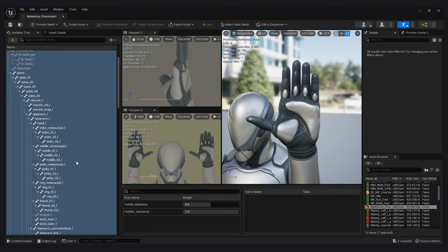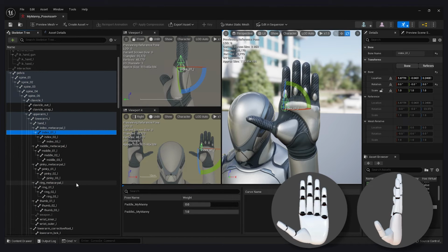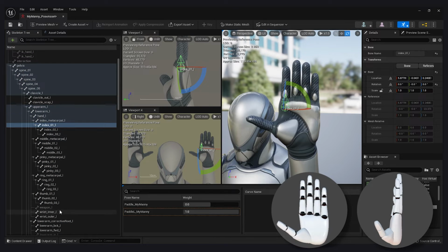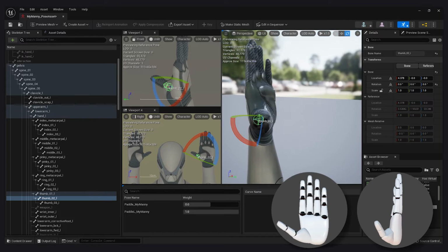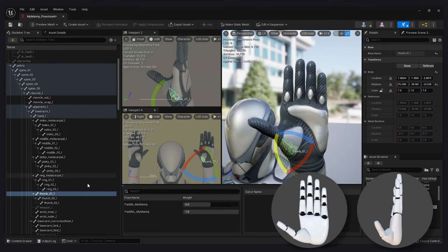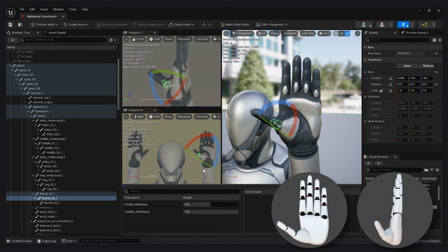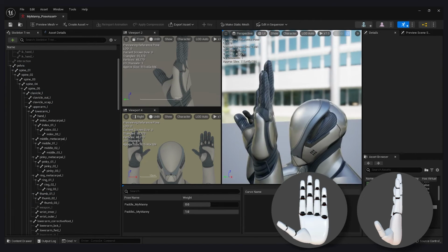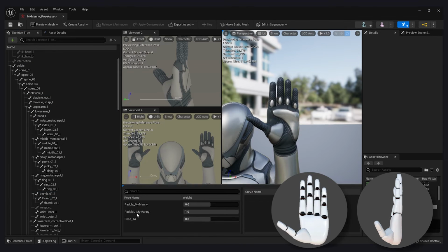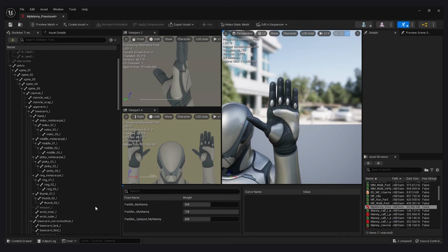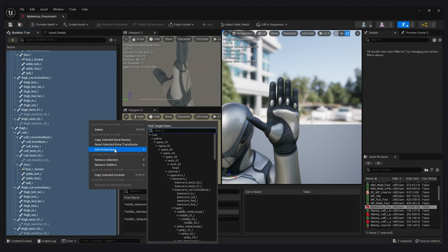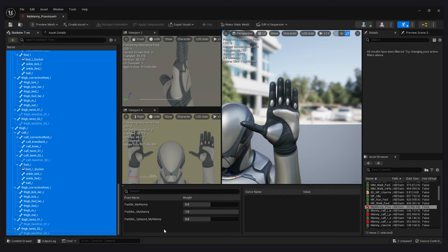The next pose we want to create is the pedal L splayed pose. Again, we are keeping the fingers as they are and just adjusting our thumb. So what we want to do for this is we want to rotate the base thumb joint out away from the palm as far as possible. Once we have something we're happy with, we'll just go ahead and create the pose asset for this pose. And again, once created, we will just go ahead and reset the bone transformations.